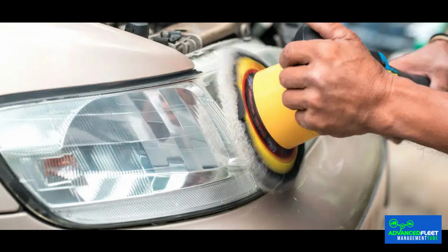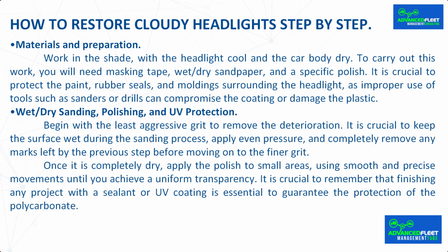It is essential to identify the cause of the problem before proceeding with sanding. A headlight may have poor exterior cleanliness, oxidation in its structure, internal fogging, cracks, malfunctions, or burned out bulbs. Each case requires a specific solution, as polishing does not repair a crack, dry internal condensation, or correct a misaligned beam. How to restore cloudy headlights step by step.